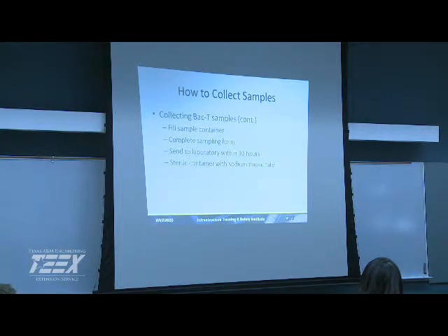Best management practices is to start the preservation process, and that benefits you as a utility operator or owner, because you're minimizing the chance of what we consider to be a false positive. Right now, if you have one microorganism in there, your presence-absence test should test for it. But then if you have to go and start plating it out afterward to determine what you actually have, you're increasing that, because you're still in a growth phase.